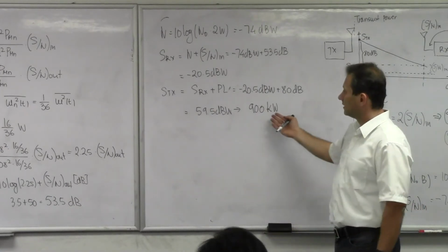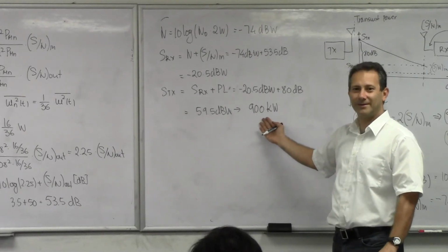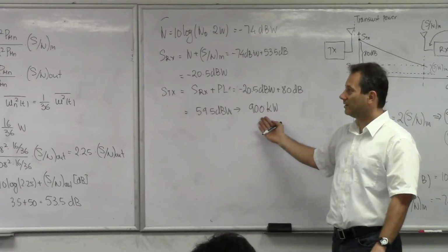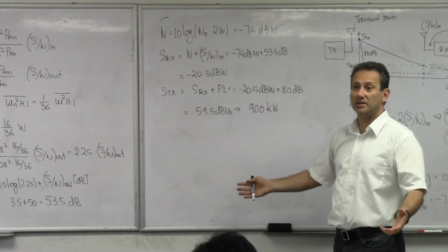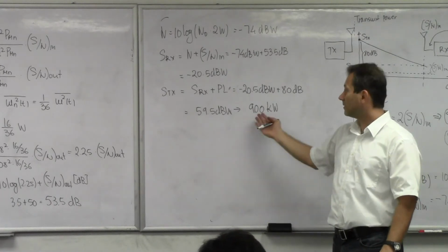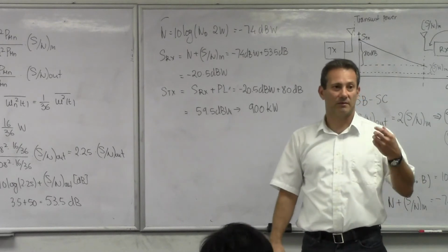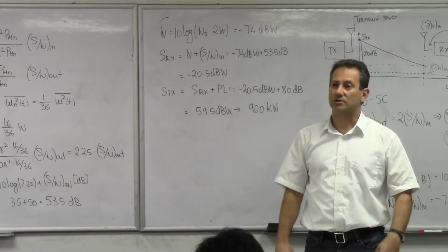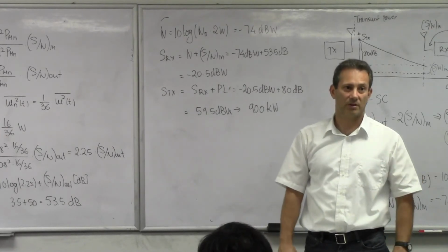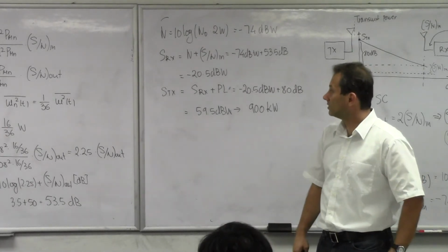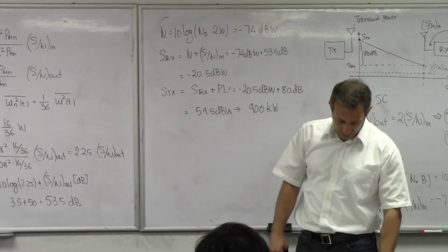And you can see that this is reflected dearly in your power bill, because you're sending a lot of power, which is essentially wasted. Your carrier power requirements go up, but where do you recover it? You recover that in the fact that your receiver is now costing $5 or $2, because it's a single diode that drives the capacitor. So it's not a complicated receiver, and you can easily demodulate the signal.